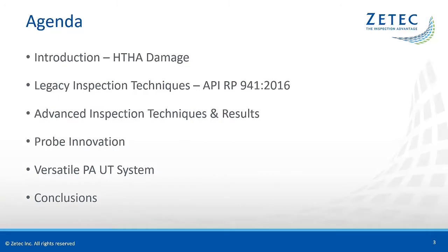Thank you, Michael. Hello, I'm Guy Moss, and I have the pleasure of presenting this webinar on advanced ultrasonic techniques for HTHA detection and assessment. This is our agenda for today. First of all, I will give an introduction on HTHA and on the specific NDT inspection challenges related to this damage mechanism. After that, I will give a short overview of legacy inspection techniques for HTHA as indicated in previous editions of the API Recommended Practice 941.